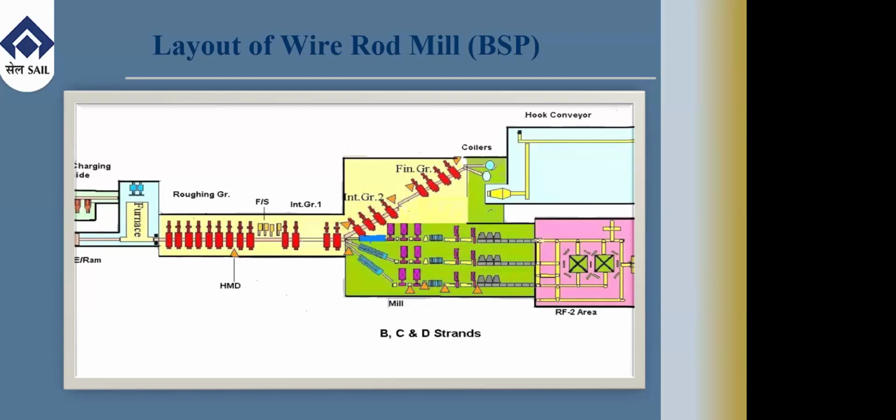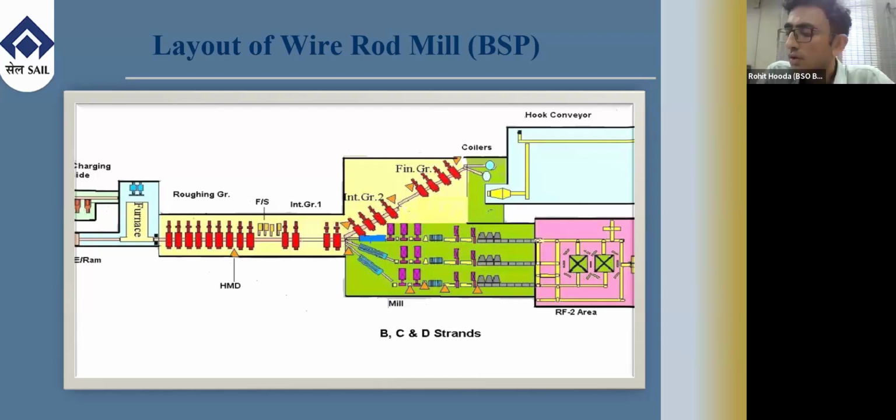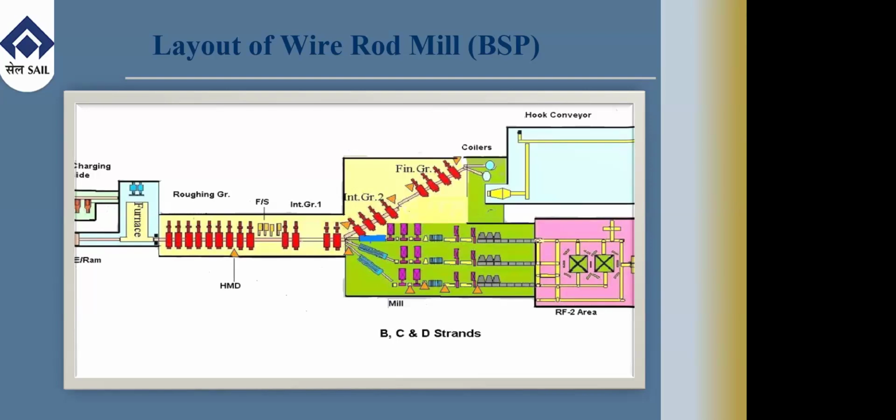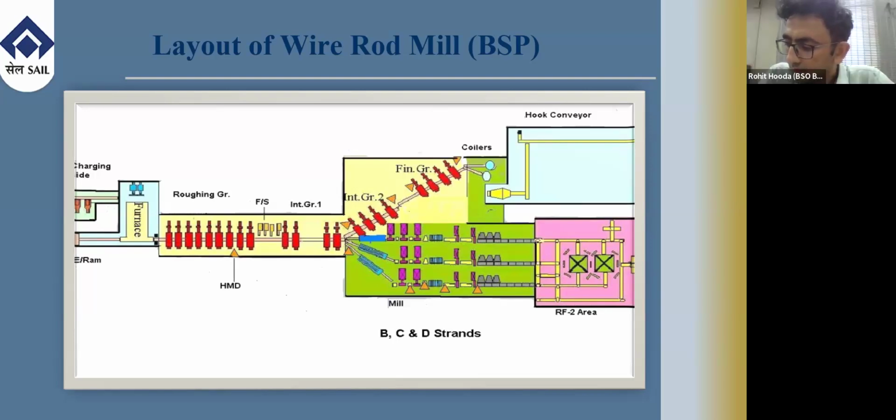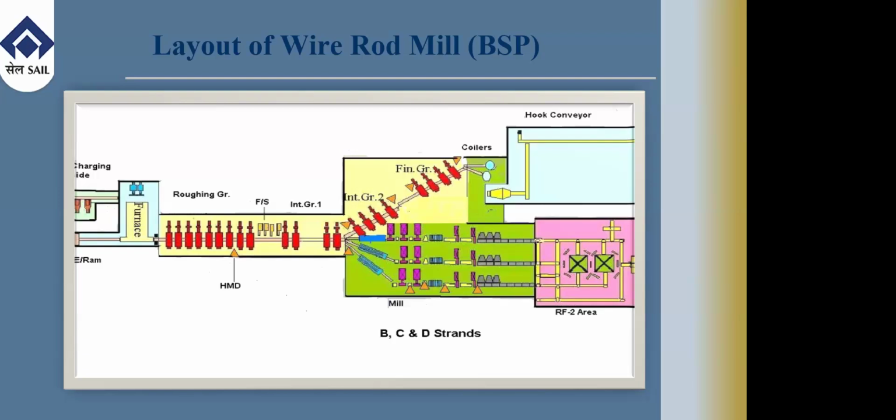It is because the hardness and strength of our wire rod was very high. The UTS was coming around 500, whereas the requirement was, I think, 400 max. Again, because of the old technology of the wire rod mill, this requires dedicated hoods on the conveyors, which promote slow cooling, which is not there in our mill.